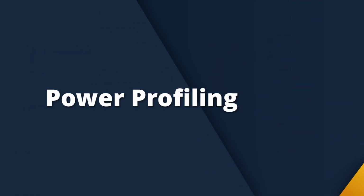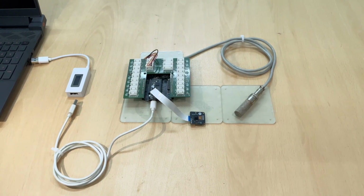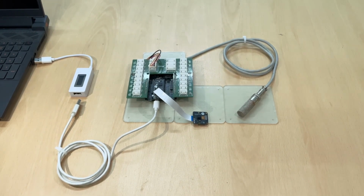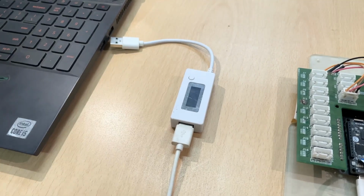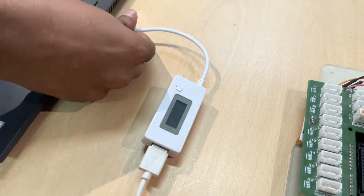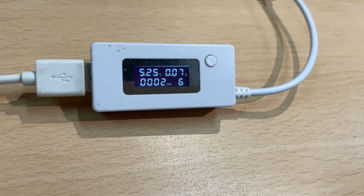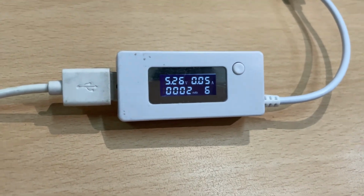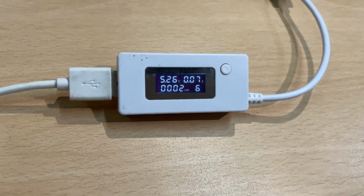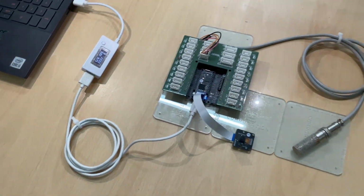Now we are showing our power profiling setup, which consists of N-node, power meter, and laptop to view the serial output. Power meter captures the current and consumed power in terms of milliamp hours. All our experiments have included all these components along with power bank. With the help of this setup, we were able to study the power consumption and duration of each major functionality of the system to decide the optimal clock speed for them.